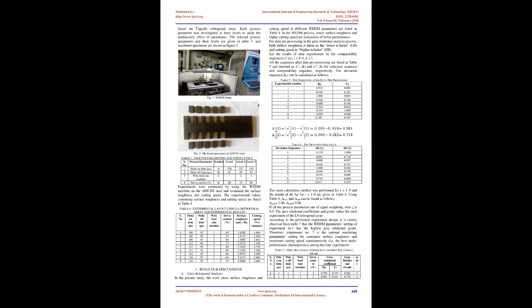For experimental work, the experiment has been done on an Electronica Sprint Cut Wire Electric Discharge Machine, WEDM, as shown in Figure 4.1. In this work the workpiece material has been taken as a flat having dimensions 150 x 50 x 7 mm thickness. Experiments were conducted on AISI D3 steel material mounted on a WEDM machine tool as shown in the figure. The cutting areas of the specimens are 10 x 15 x 7 mm thickness. In the current work, 4 process parameters such as pulse on time, Ton, pulse off time, Toff, wire feed rate, WF, and servo control, C/S, were selected for conducting the experiments.